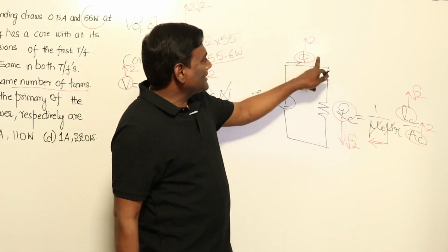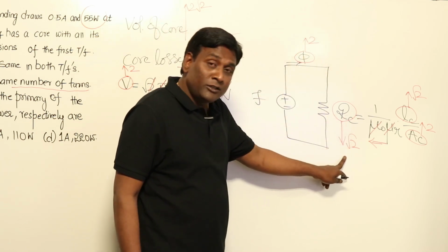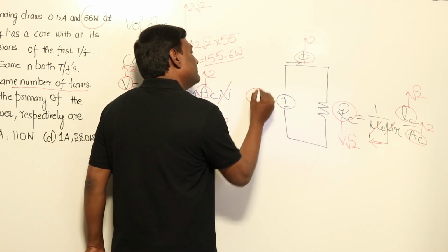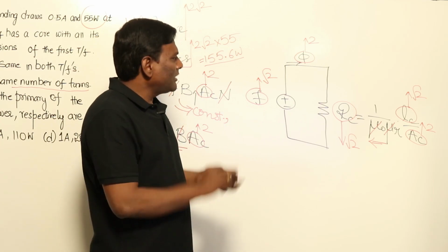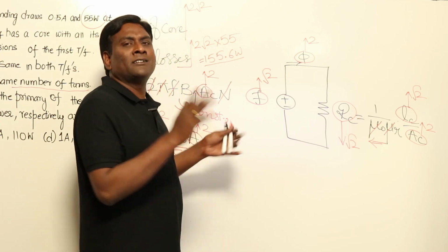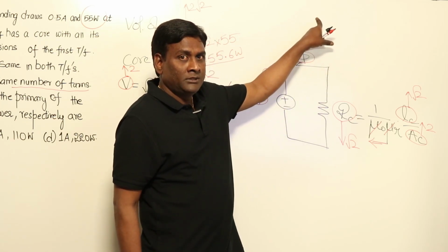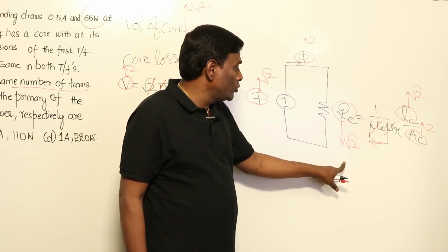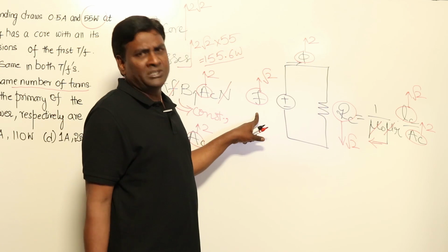Now flux should be increased by 2 times and reluctance is getting reduced by root 2 times, so my MMF should be increased by root 2 times. Getting my point, right? For example, let us think of it as an electrical circuit. In an electrical circuit, if the current is doubled and the resistance is reduced by root 2 times, what about the voltage? It should be increased by root 2 times, in the same way.